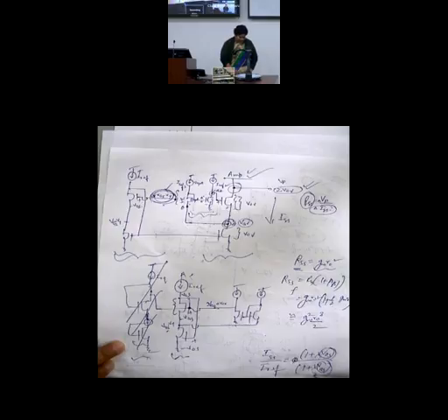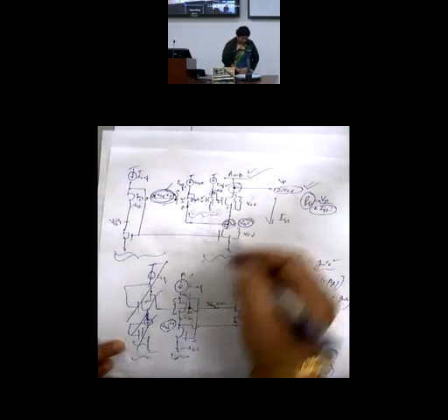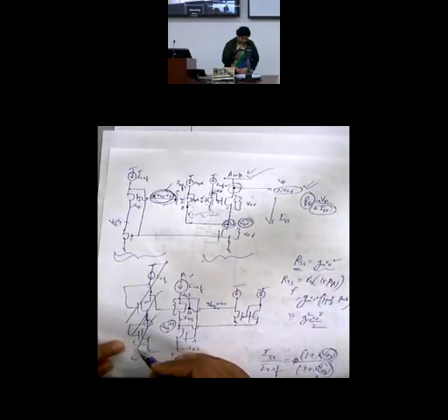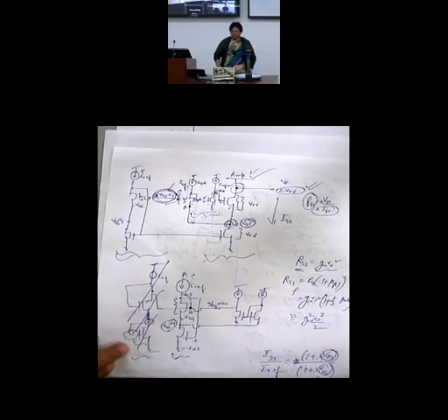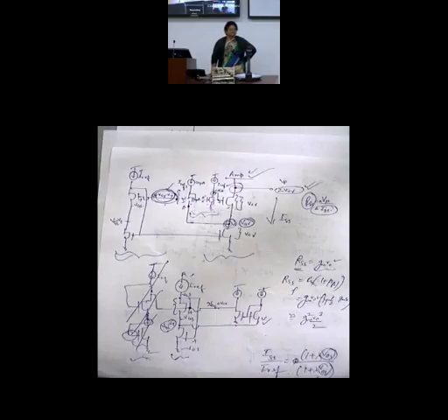So as far as possible, this is 1 V overdrive, this is 1 V overdrive. I should try to have this also as 1 V overdrive. If this is not giving me that, I would rather go for this solution, because this enables me to have 1 V overdrive.